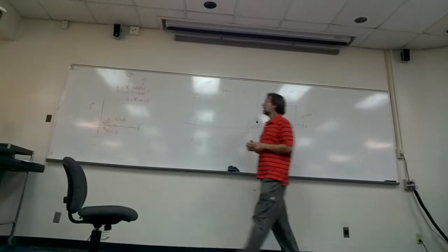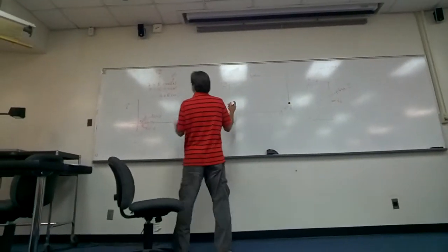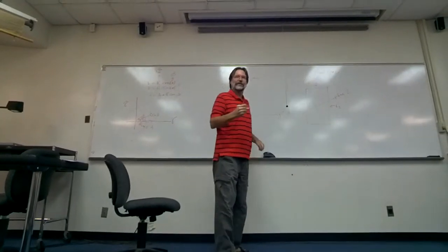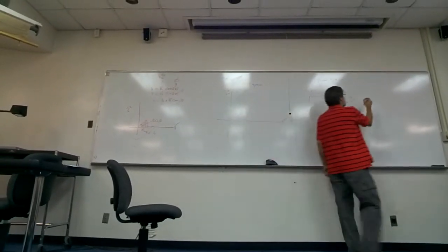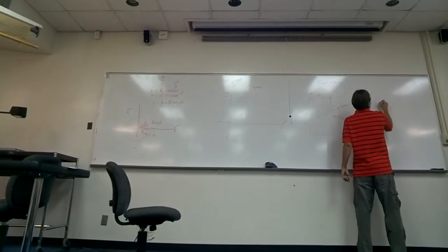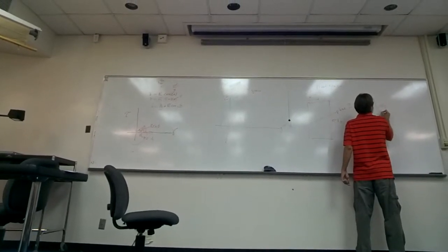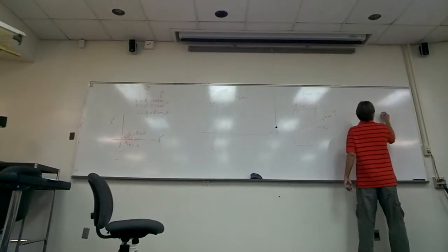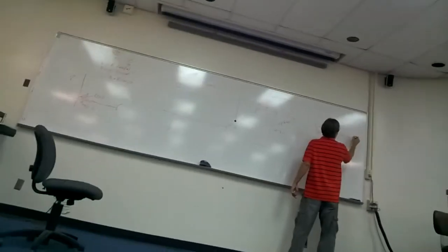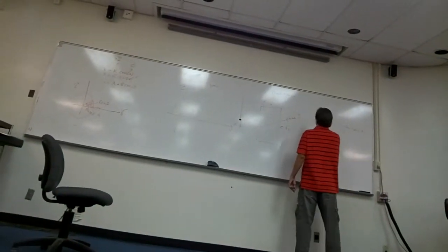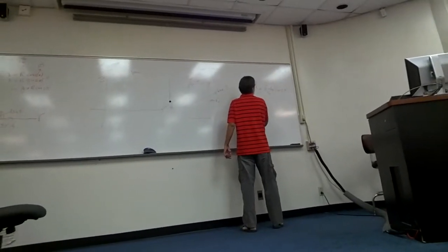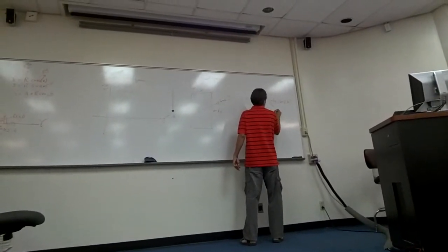What Mohr's circle does is plot, which I now don't have. Now I've got to remember it myself. See if I can remember this. It should be sigma equals sigma 1 plus sigma 3 over 2 plus sigma 1 minus sigma 3 over 2 cosine 2 theta, and tau equals sigma 1 minus sigma 3 over 2 sine 2 theta.